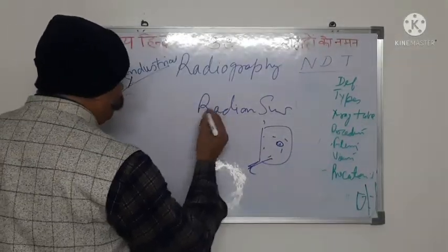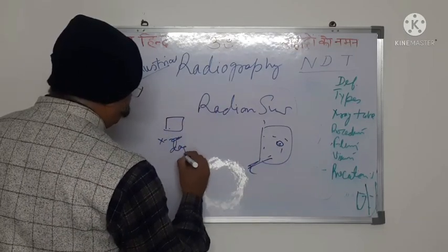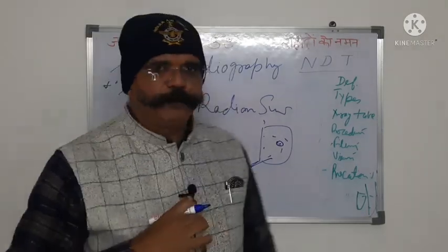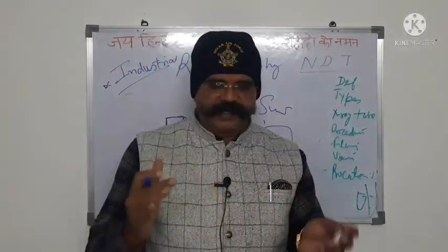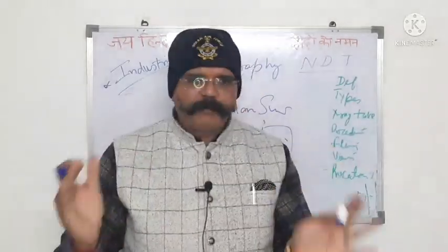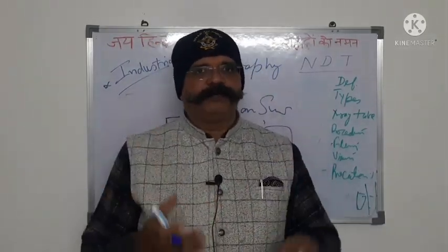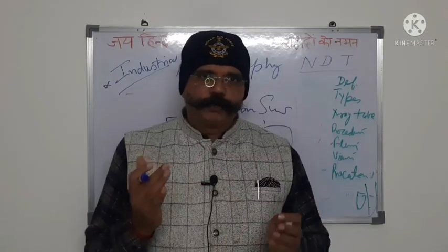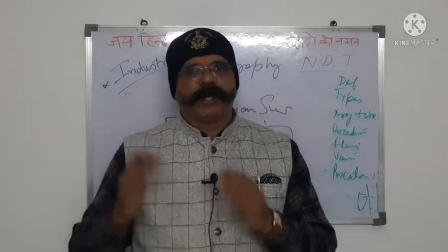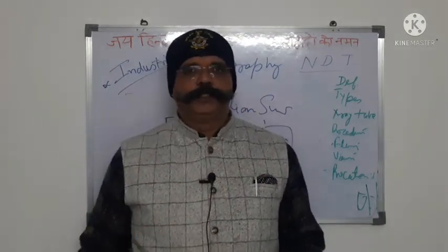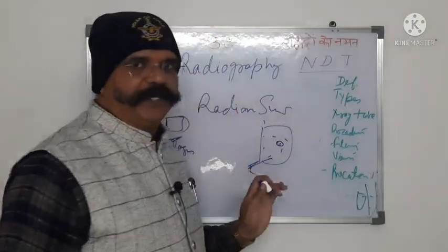All the operators are given an X-ray dosimeter. They have to place it on their body or chest when they are working on this radiation job. So whatever amount of radiation they are receiving, by mistake or by virtue of their job, that is to be monitored in this dosimeter. And on a monthly, quarterly or yearly basis, the cumulative dose can be monitored against each operator.